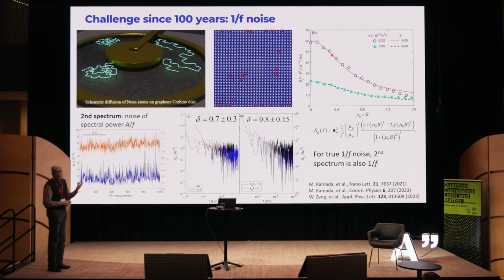So you will get anisotropic mobility fluctuation in your system. And in this case, when you have this kind of anisotropic mobility fluctuations, then there's a special point. If your mobility times magnetic field is 1, the noise will vanish. Of course, in practice, in our case, it doesn't fully vanish. In our case, the correlation between the different directions of the mobility fluctuation is not perfect. And in this case, you don't really get this full suppression of the noise.